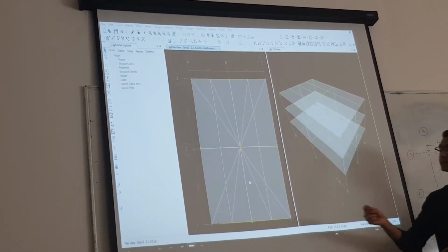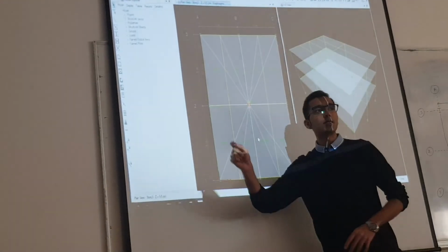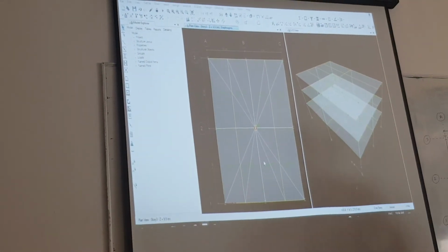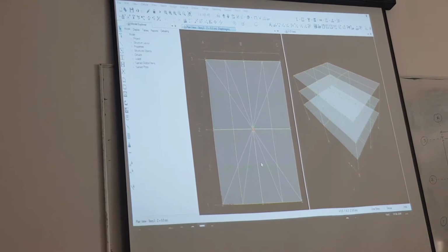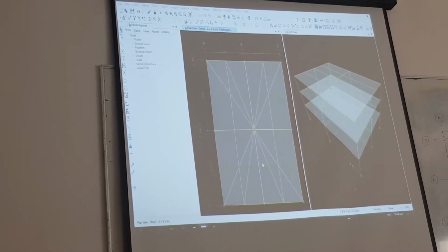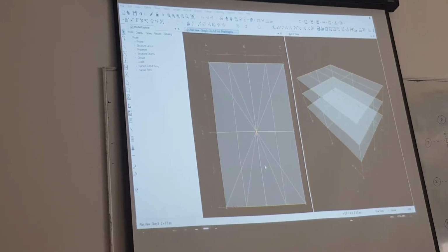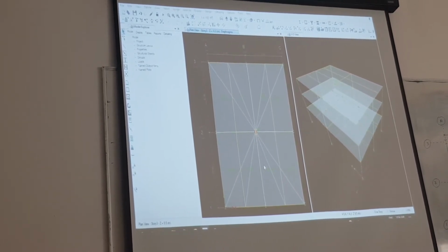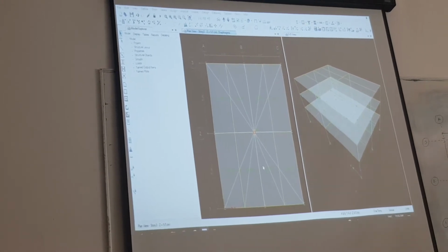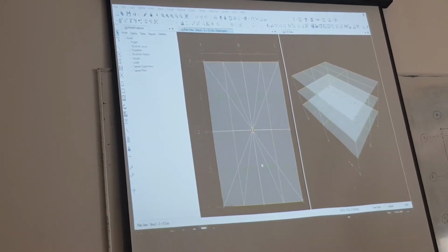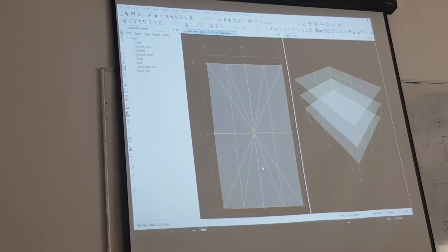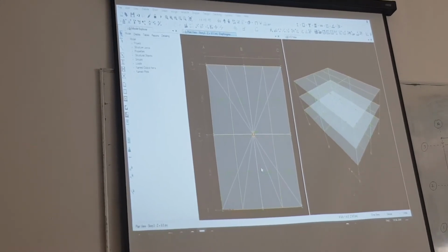The second benefit is that you can see where the center of rigidity is for each story. We select the whole story as rigid from the plan view of the story. Yes, this is what we want. No, that one was the property. This time it is the assigning of those diaphragms. Assignment. We have to assign something.